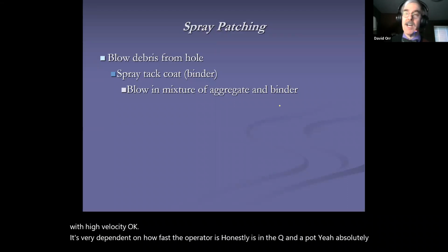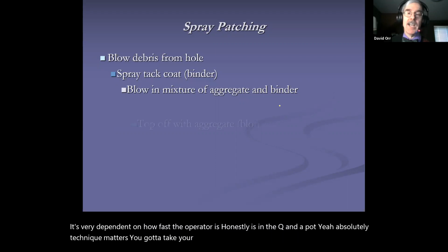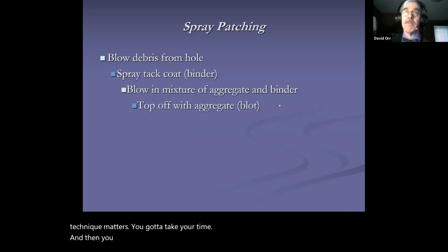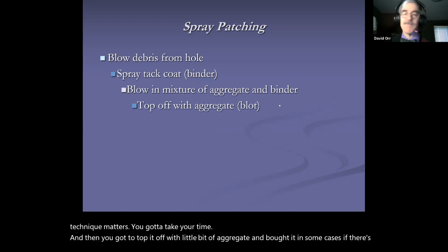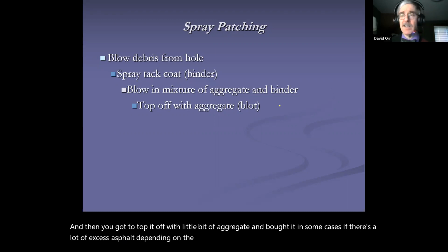You got to take your time. And then you got to top it off with a little bit of aggregate and blot it in some cases if there's a lot of excess asphalt, depending on the mix. And you got to make sure everything is clean. At the end of the day, you got to make sure it's clean.